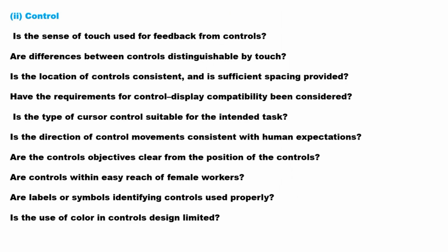E. Control. Is the sense of touch used for feedback from controls? Are differences between controls distinguishable by touch? Is the location of controls consistent, and is sufficient spacing provided? Have the requirements for control display compatibility been considered? Is the type of cursor control suitable for the intended task?